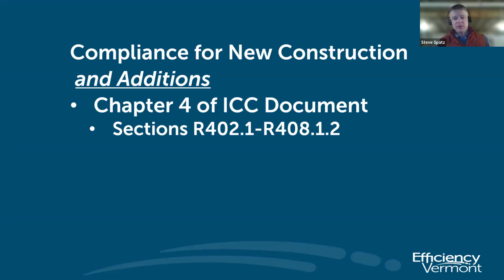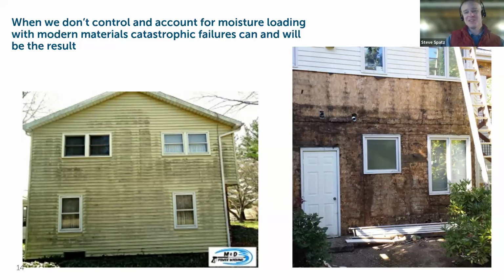We are just unpacking a beautiful package here for you, Bruce, of how to come to this outcome. So I'm going to talk about this in a lot of detail as we go through the rest of the content here today. Ultimately, what this is right here is OSB as a sheathing on these wall assemblies that has been seeing a high amount of both vapor and liquid water over time, and the inability of that material to dissipate that water and that moisture has accumulated to the point where you just get catastrophic damage. So that's a lot of what I'm talking about here today, is how to prevent and mitigate against this potential outcome in the long run through material choice and just the dynamics, the physics at play that can get to this point if you're not thinking about them.